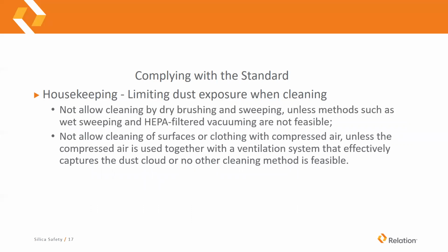Do not allow cleaning of surfaces or clothing with compressed air unless the compressed air is used together with a ventilation system that effectively captures the dust cloud, or there's no other cleaning method feasible. And also remember, when we're using compressed air to clean anything, it has to have a chip guard, and your air pressure has to be limited to 30 psi. But whenever you have silica dust on you, you don't want to just spray somebody off with air and recreate that dust cloud.